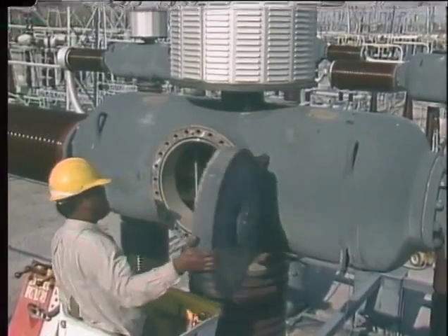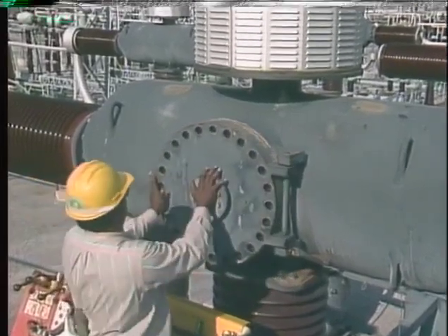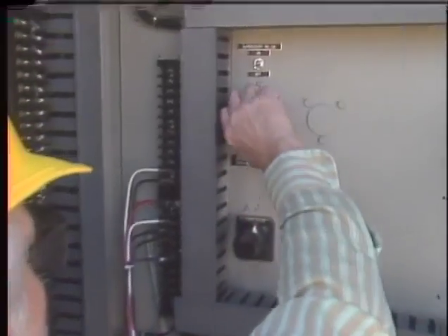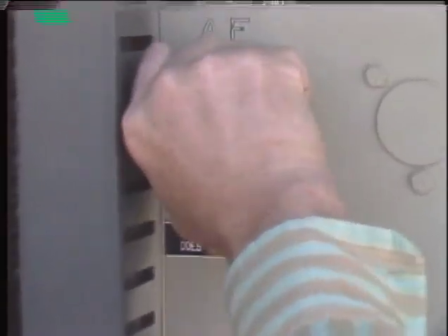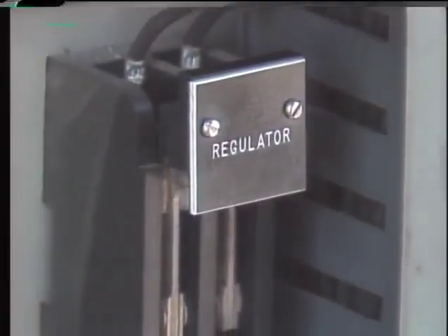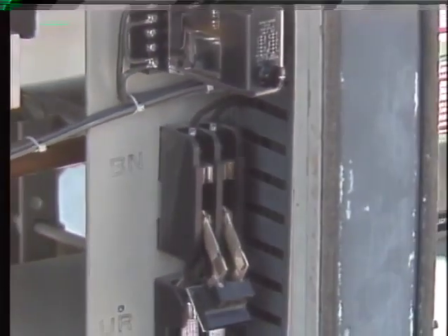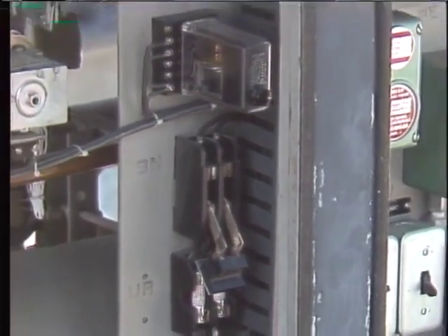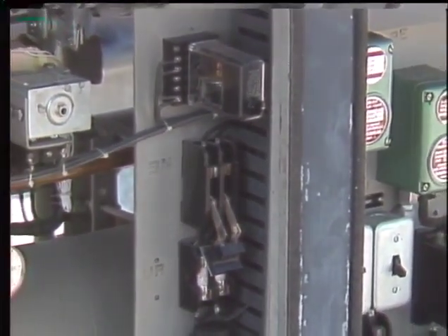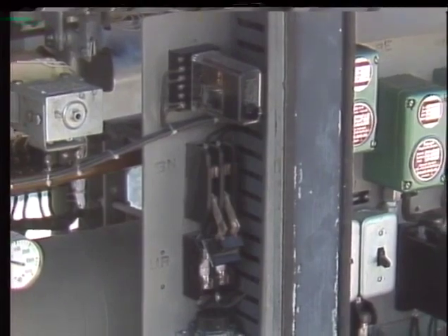After the interrupter maintenance is done, the heads are closed back up, and system pressure is restored to normal. After the pressure is restored, the breaker is closed. Air pressure is allowed to return to normal again. Then the pressure regulator is de-energized so that breaker air consumption can be checked. Air consumption is the amount of air that is used to trip the breaker and extinguish arcs.